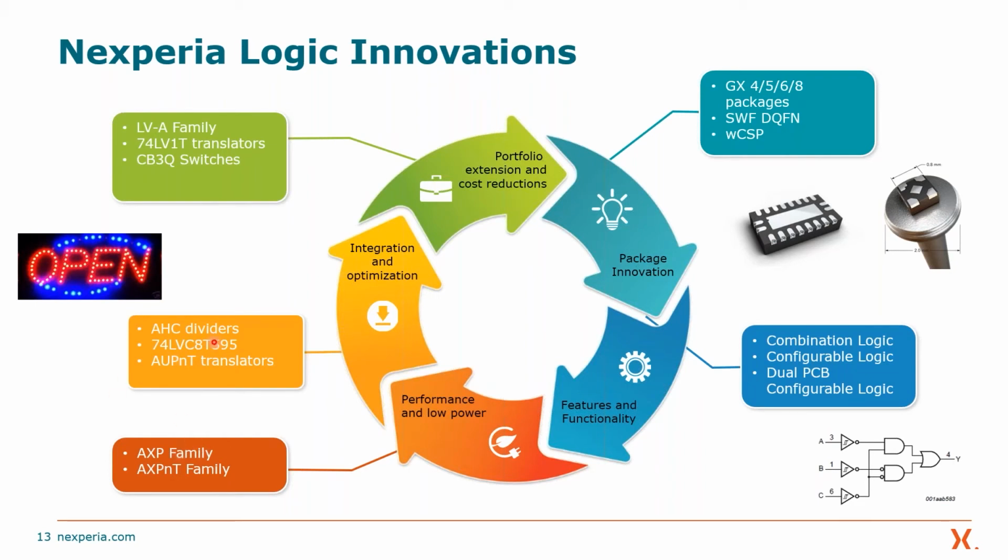Other things are integrated solutions. For example, there's a picture of the LED sign here, very popular. Everybody designs it essentially the same way. Your microprocessor at 1 voltage talks to a shift register, which talks to power MOSFETs, which drives the LEDs directly. Because everybody did it the same way, we developed a single part, which essentially integrates all those together. The translator plus the shift register plus higher output drive, because that's the way everybody did it.